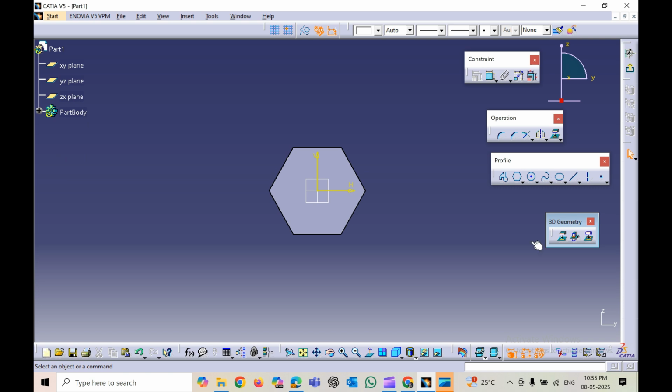With my experience, I can say these commands are very useful when it comes to STEP files, and the type of files which we receive from the customer, which are a dummy solid. It doesn't have any features inside it. So in such cases, for remastering the model, these 3D geometry features are mostly useful. So let's discuss this command one by one.